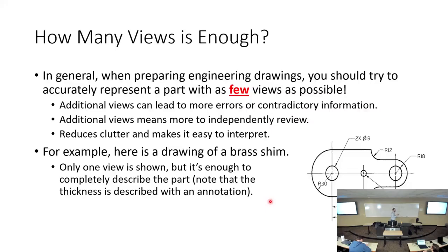And I'm sure the math professors are like, well, it doesn't really matter. You're right, it doesn't matter, but we're building it. So what makes sense? I can go to Lowe's and buy a 1/2-inch drill bit. So that's what it's going to drill: a 1/2-inch diameter hole. We tend to spec out holes in diameters, but when it comes to arcs or fillets, we tend to spec those out in radii. Okay. All right.